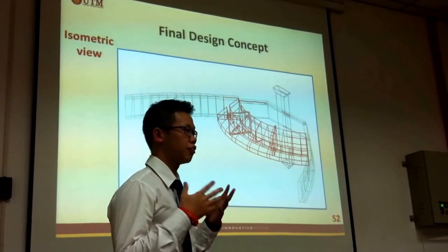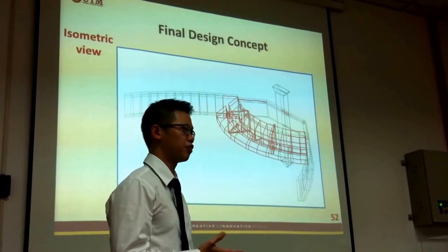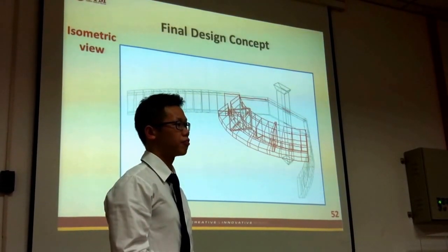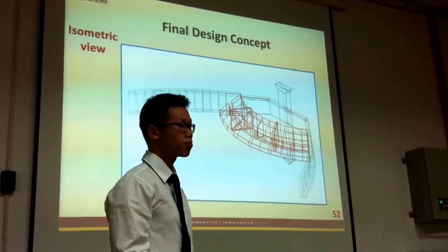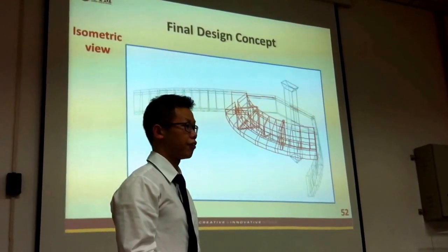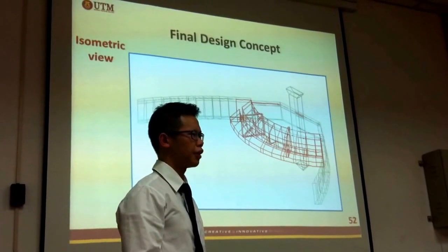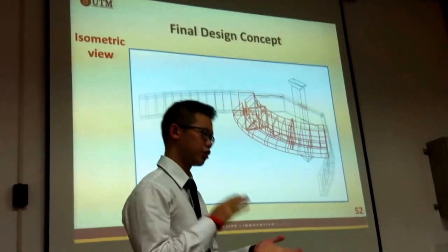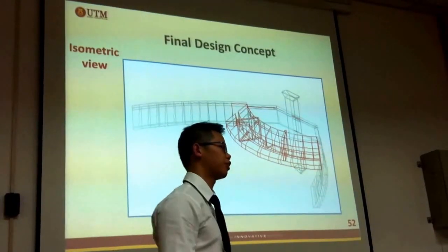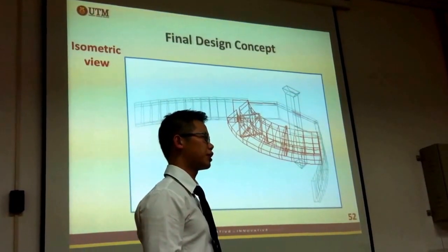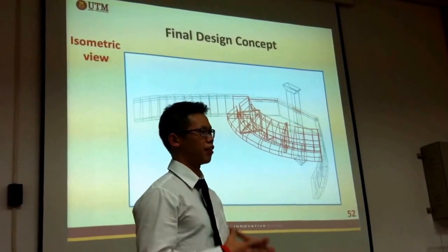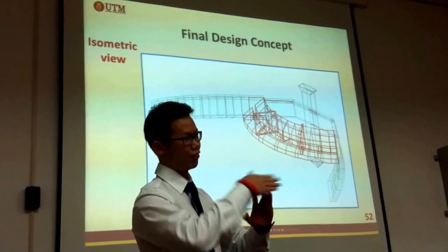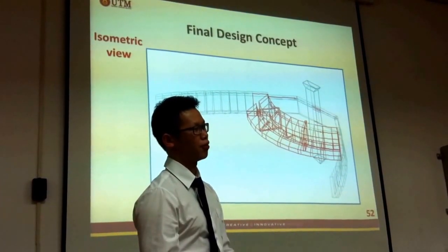Whereas Wave Dragon is really catered for European wave conditions, which are really high, like 3 meters and above. Your ramp is similar to Wave Dragon's, right? It's with an angle, but basically it only has one reservoir. It has to overtop from the ramp into the reservoir. But for us, because we are designing this wave overtopping device, if our reservoir is too high, the waves won't be able to overtop. So that's the problem that we face here.